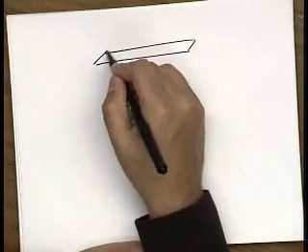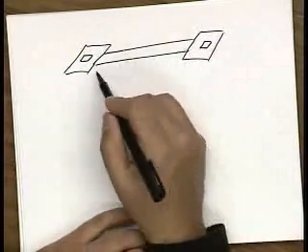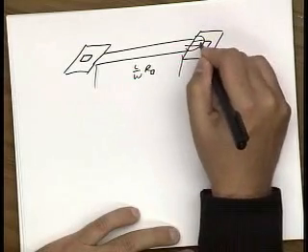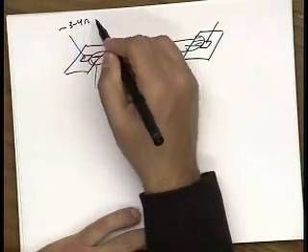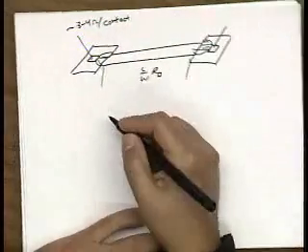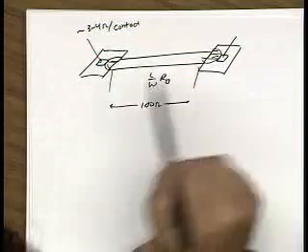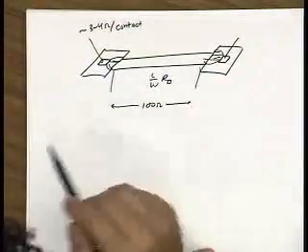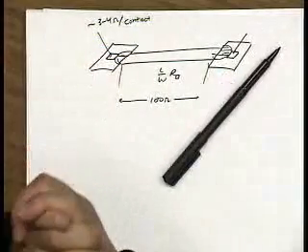So let's say I build a resistor, and then I need to make contacts to it. So I have, let's say, a piece of polysilicon that's bigger, and then I put my contacts here and here. Now inside this region, once I'm inside here, I know the resistance is roughly L over W times sheet resistance. But over here, the current is going to spread out, and there's also contact resistance. The contacts themselves might be 3 to 4 ohms per contact. And so let's say I'm building a 100 ohm resistor. And if I'm just sloppy and I just put down one contact here and don't really take into account the effects of non-uniform current flow here and here, I may end up systematically getting a mean value of 110 ohms instead of 100 ohms, right? Well, that's my fault. I just didn't do a good job.